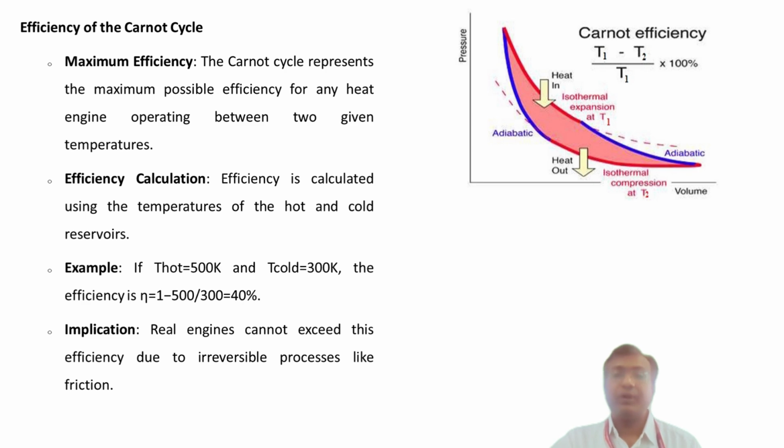Now we will see the formula for the efficiency of the Carnot cycle. The efficiency of the Carnot cycle is a very crucial concept in thermodynamics because it represents the maximum possible efficiency that any heat engine can achieve when operating between two given temperatures. This means that no real heat engine can be more efficient than a Carnot engine working between the same hot and cold reservoirs. First, let's recall what efficiency means in the context of a heat engine.